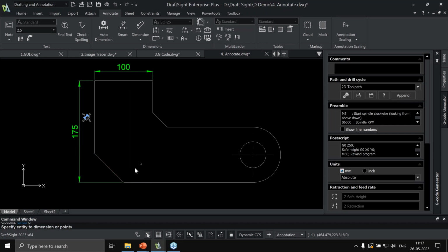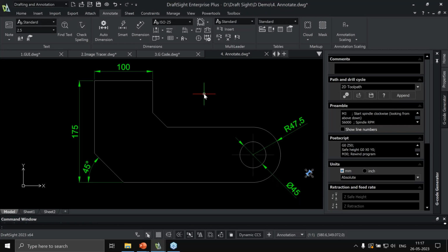me the results. It might be an aligned line, and it will show me a parallel dimension. When I move the cursor down, I'll get the horizontal one, the vertical one. I can define what type of element I want, or with the same tool I can get the angular dimensions. It might be an inward angle or an outward angle. It recognizes an arc as a radius, a circle as a diameter. So like this we can fine tune to a larger extent.